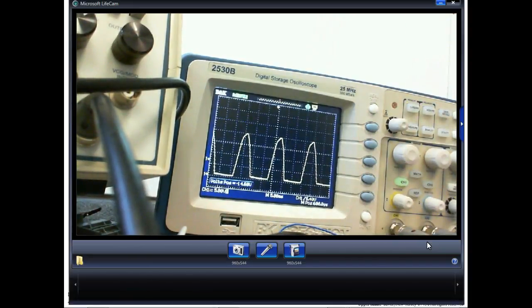now I'm going to measure this peak voltage. Now we calculated what it was, right? You understand? We expect it to be 17.1 volts. But now we can measure it with my scope. I can't measure it with my meter. My meter is going to give us an average. All right, you understand that?